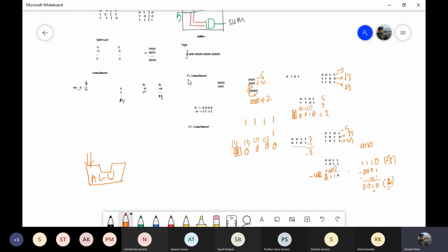So far we had been looking at only one bit, like the A bit and the B bit, but the ALU is going to take significantly larger numbers. If it is taking 4 bits, it's going to become a 4-bit processor. And it is not only going to take 1 line, it is going to take 2 lines, and the second line is going to be the B series. So B0 to B3 is 4 lines, B0, B1, B2, B3, and A0 to A3 is once again 4 lines. This small piece here is the 4-bit binary adder subtractor, or the binary arithmetic logic unit. This is a small component of a microprocessor, and the microprocessor that we're going to talk about today is the 8086 processor.